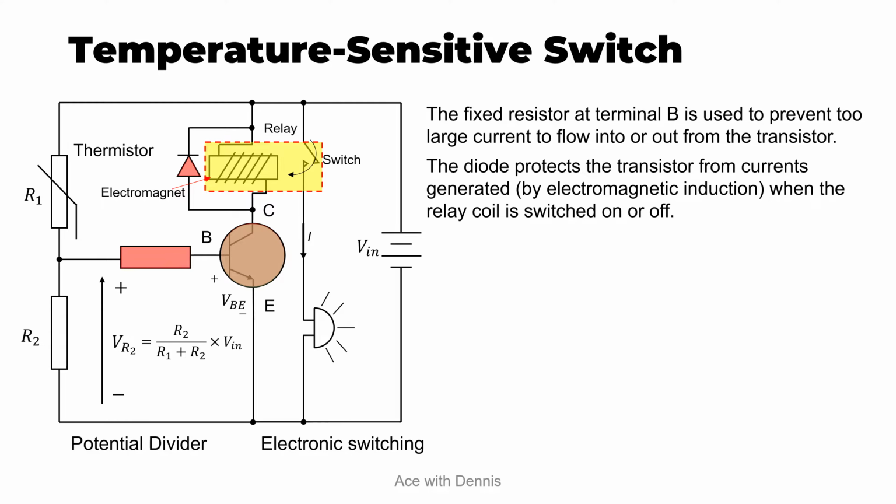So that's why in this circuit the bell has to be connected separately from the transistor. Because of this, a more powerful bell can be used, as the current in the bell does not have to flow through the transistor. As I mentioned, the transistor only uses a very small amount of current in the milliamps range. This principle is used in automatic fire alarm systems.